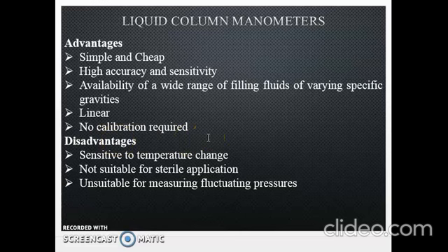On the other hand, the liquid column manometer has certain disadvantages also. The disadvantages are as follows. They are sensitive to temperature change, and if the liquid is volatile, the manometric liquid will show different zero readings. They are not suitable for sterile application as they are in direct contact with the pressure measuring nodes.